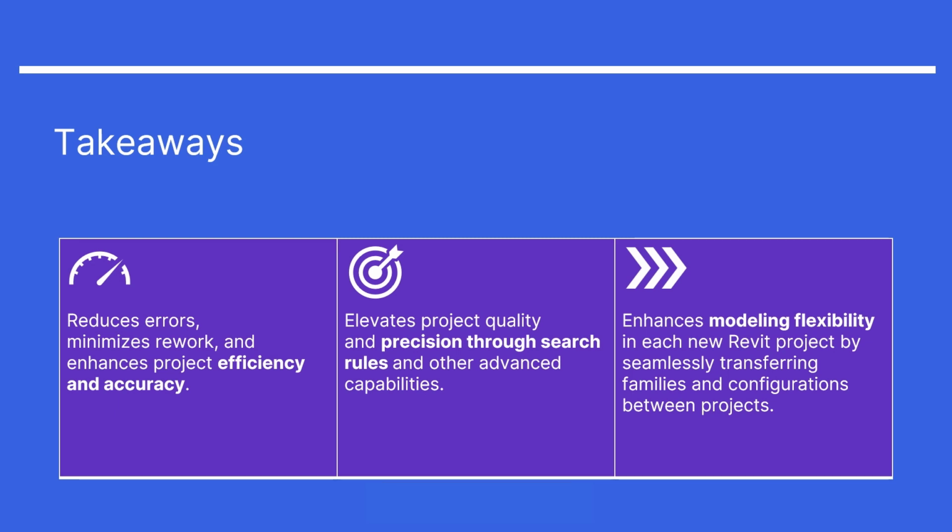We can press update elements, the software detects the new shape, and it will adjust not just positioning, but the family parameters as well automatically. And we will always be assured that everything is done precisely and accurately. Utilizing smart connections in our workflow, we avoid lots of tedious work, we drastically reduce the repetitiveness, and we're able to concentrate on valuable tasks.